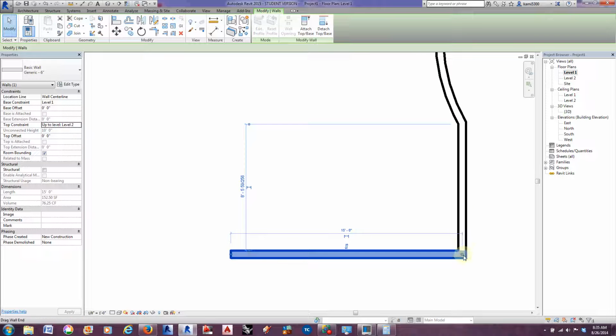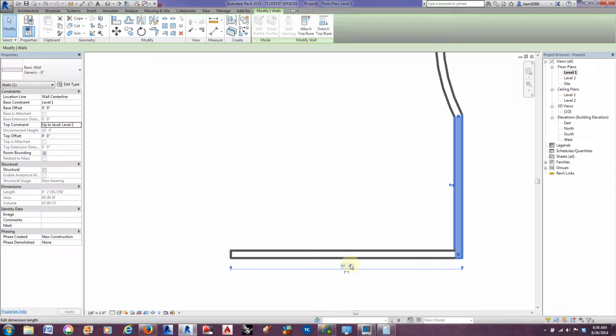And say we don't, yeah, it's not going to let me change that temporary dimension. There we go. Maybe I want it to the outside of that wall instead. Just go 15 feet. And also when you keystroke in dimensions, it recognizes feet and inches. So if we go 15 and then a space and say 6, it'll do 6 inches. And if you want that to be even more specific, 15, 6, and maybe 1/3, you just put a space in between and it recognizes that.